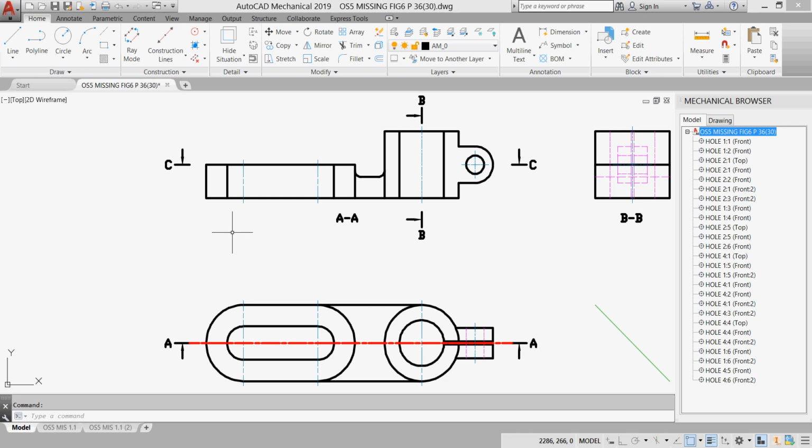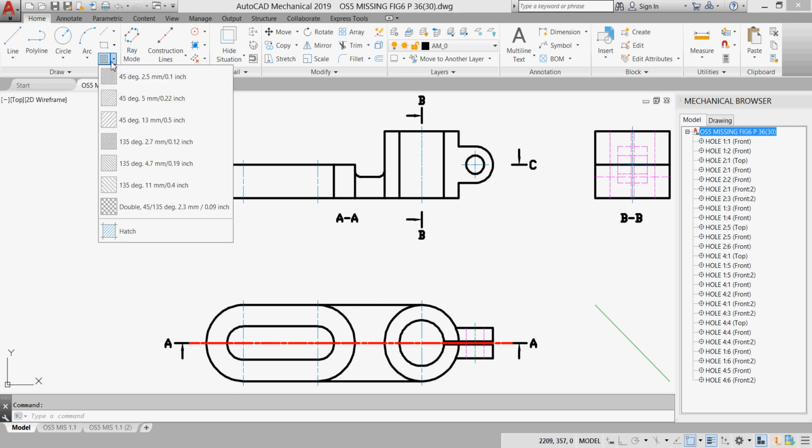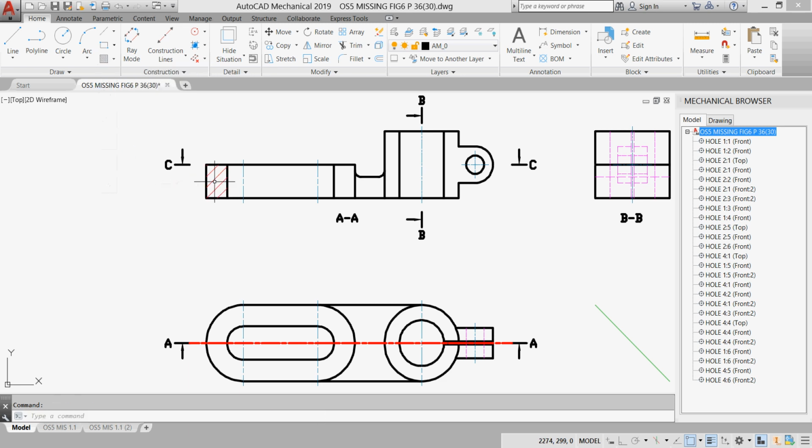Okay. Now I'll create hatch lines where we have our cutting. So it will be here, enter here, enter here, enter here. Shall we have the cutting or not? Let us see. So this is the thickness of my slot. The other way is the thickness of my slot. Here we have a web. Even if it cuts along, we don't put hatch lines.